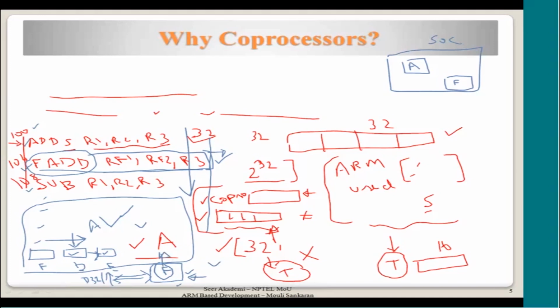I just want to give you an overview of where the whole thing is working. ARM instructions are all there, and in between, the floating point instructions are embedded. They also occupy a 32-bit wide instruction, but in a different format than typical ARM instructions. So the ARM processor knows it is not its instruction, and it will look for any takers in the system.